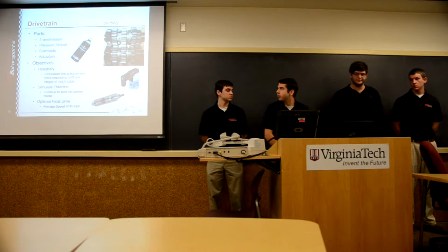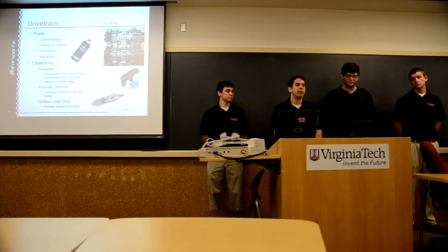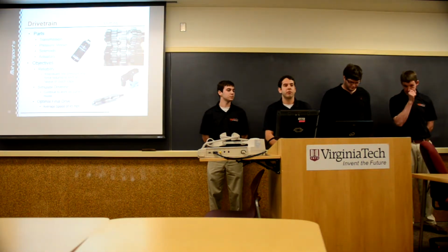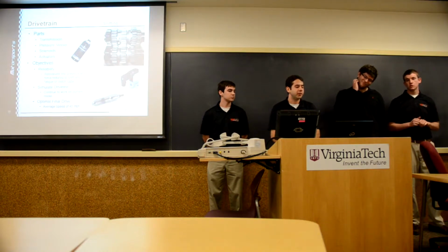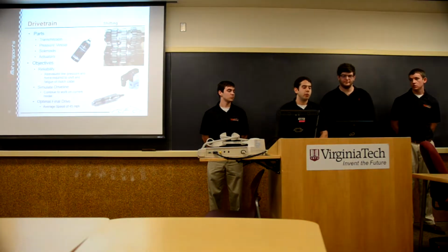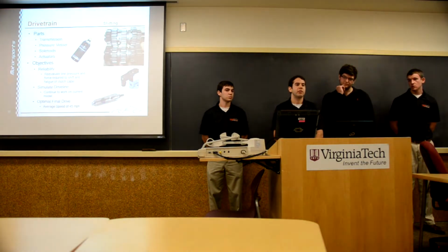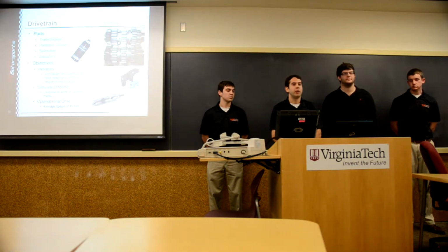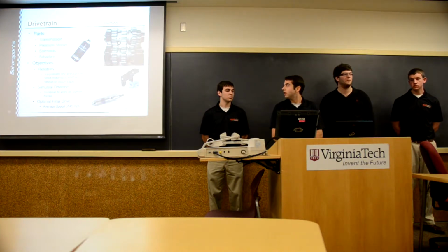For the 2014 shifting, we're going to stick with the electro-pneumatic shifting system. The parts of it are the transmission, the pressure vessel, the actuators, and the solenoids. Our objective, as with the whole team, is reliability first. With the new engine being purchased, I'm going to reevaluate the forces it takes to shift, which then determines the pressures in the lines. I'm also going to do a fatigue design on the clutch cable, as we've seen it fail in the past, and try to eliminate any leaks in the line.